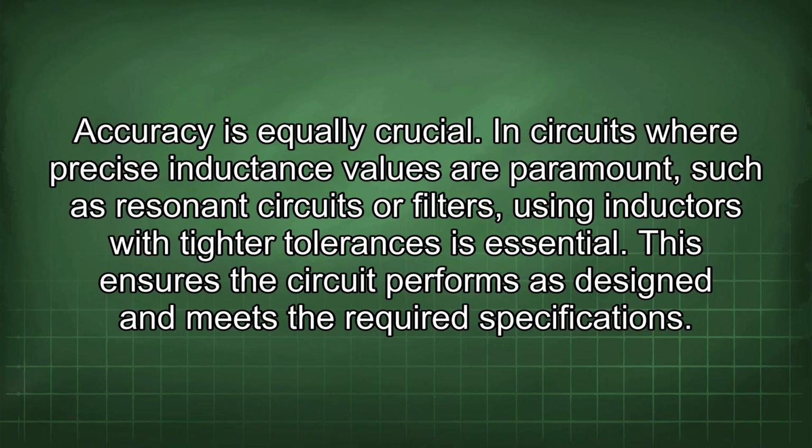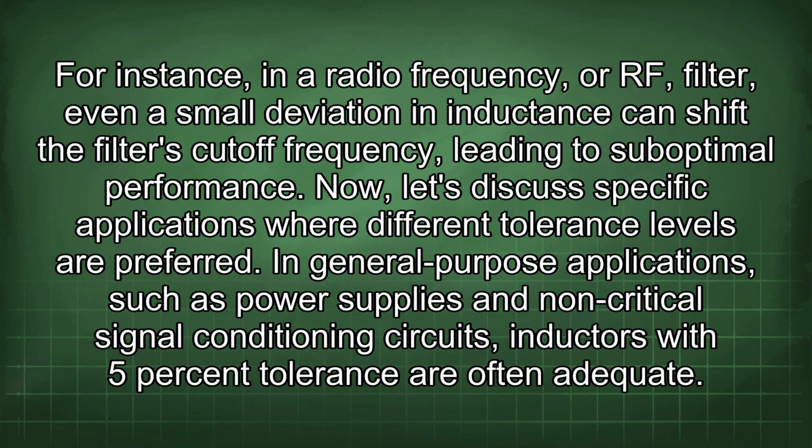Accuracy is equally crucial. In circuits where precise inductance values are paramount, such as resonant circuits or filters, using inductors with tighter tolerances is essential. This ensures the circuit performs as designed and meets the required specifications. For instance, in a radio frequency or RF filter, even a small deviation in inductance can shift the filter's cutoff frequency, leading to suboptimal performance.